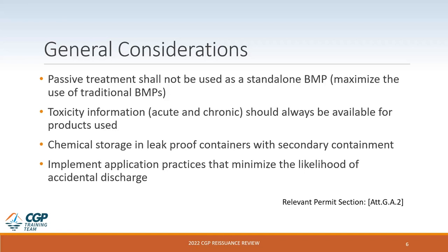Also, it's essential that toxicity information is available for any passive treatment chemicals that are used on a construction site. Both the acute as well as the chronic toxicity information should be available for those chemicals. And how those chemicals are applied and stored, it's important to ensure that secondary containment is used and that application practices minimize any potential for an accidental discharge. The goal being, again, to protect water quality and avoid any accidental discharges on your construction site.